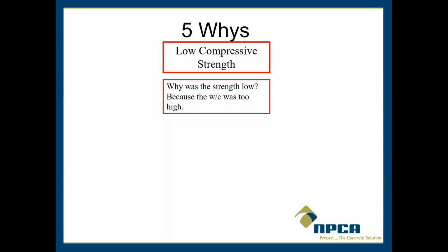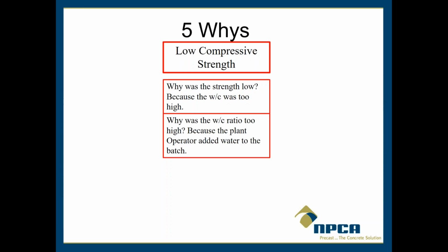So what we're saying here is that this mix, this batch that had low strength, had too much water in it, and we have discovered that in some fashion, right? This is another case of why was the strength low? Oh, because it's got too much water. I don't know that until I do some work to find out why that is. So if I know that the batch had too much water, now that makes sense. That would impact the strength, but I need to determine that. And we're not going to talk about the tools that you would use to do that, but we've determined that in this case, that's the reason.